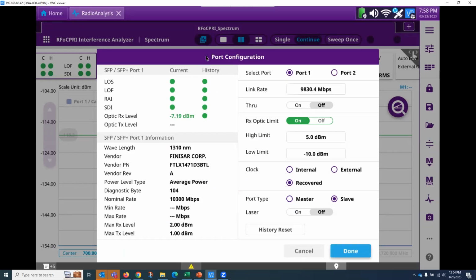And that will allow the radio and the baseband unit to talk again without seeing anything. It loses a little bit of power because we steal 3 dB of light out of it. And then next to that tap, which we can put in a picture, there is a monitor port. There are 2 monitor ports, actually: one to monitor what's coming out of the baseband unit.